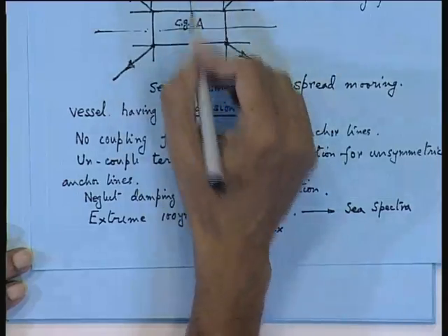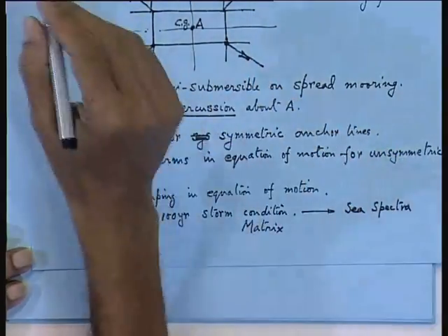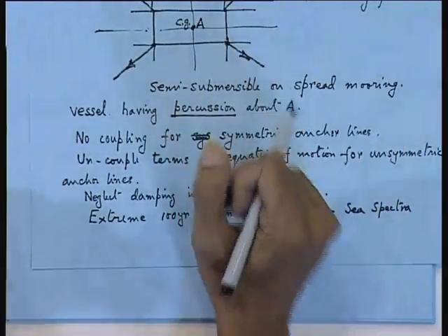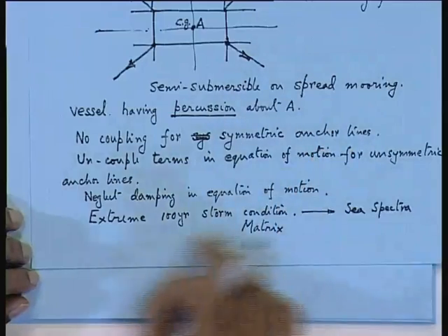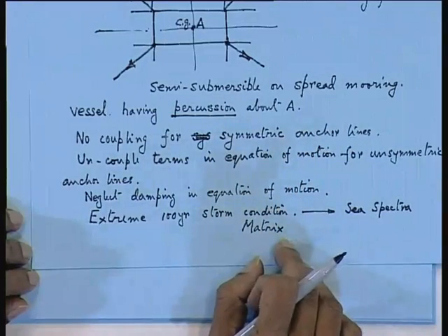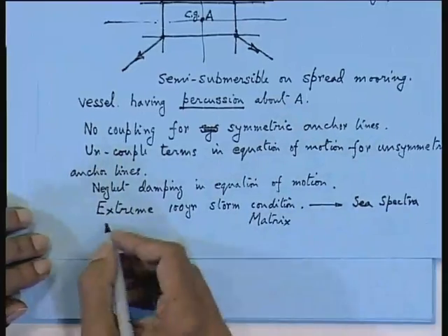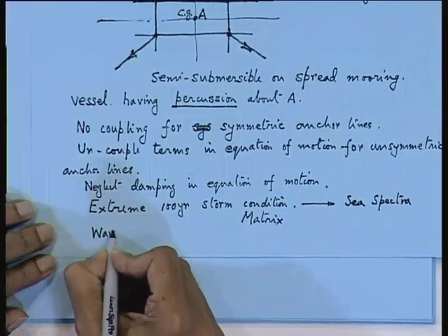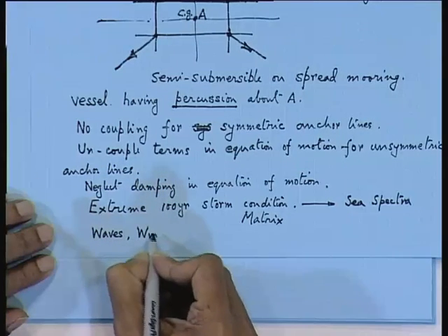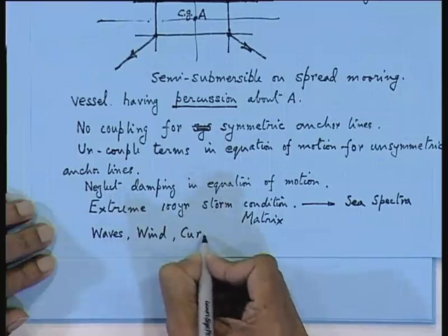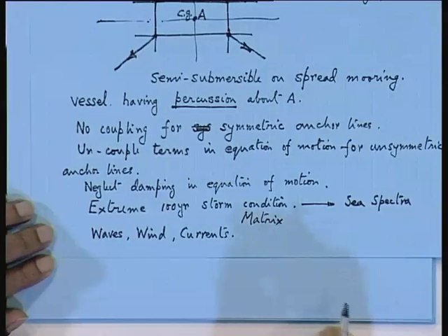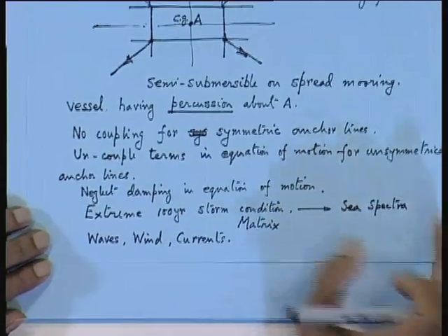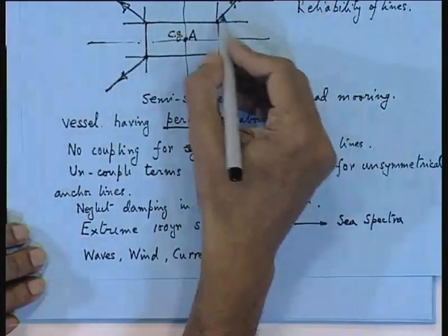options. Whenever you are doing some mooring system design, you never give a client just, say, 4 anchor lines. He will ask you to tell him the various configurations with various loading conditions. So for your extreme storm conditions, you will find all these external forces are coming because of waves, wind and current. These are the normal forces coming, of course, on floating platforms. So for all these spectra you have to calculate the maximum wave, wind and current forces, and these are summated